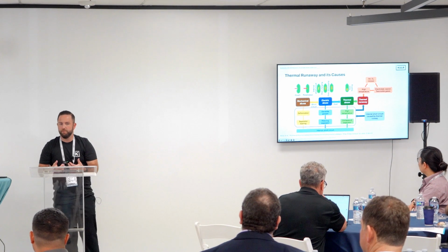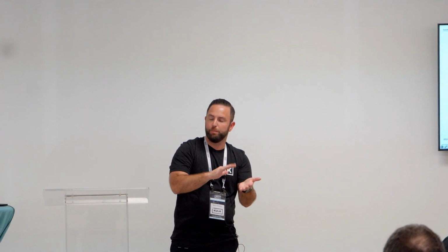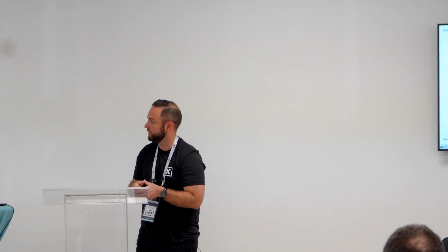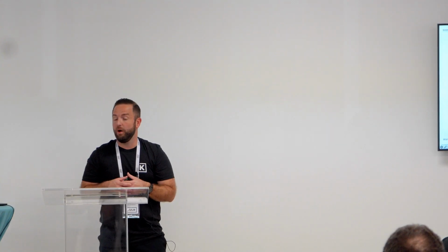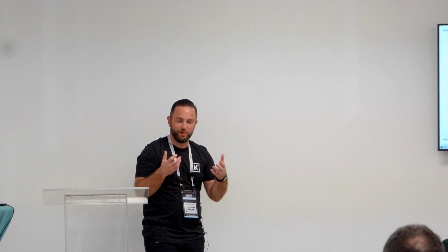An example of that you may see in the real world: without a skid plate, you could see the batteries in a car get dented or damaged if that car bottoms out and it's a lower facing battery pack. Why do we have those skid plates? To prevent mechanical abuse from happening to the battery. Think of eVTOL. A big thing you have to worry about when you're dealing with electric aviation and aircraft is impact, whether intentional or unintentional.